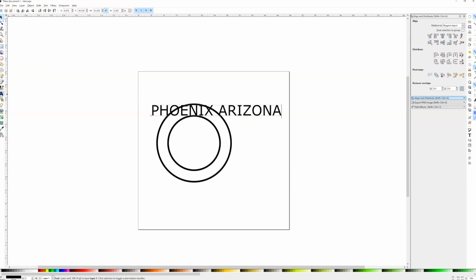Go ahead and click on the A to edit text, and then up here is the spacing. So you can go over that spacing, and we can put a 2 in there, and notice as I put a value in there, if I put a 5 in here, it keeps spacing it out more.